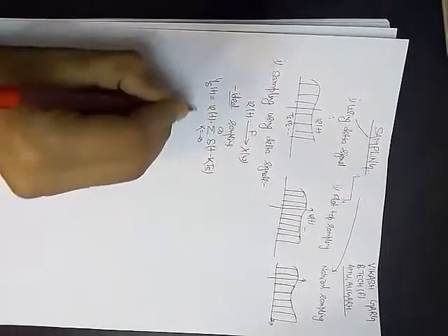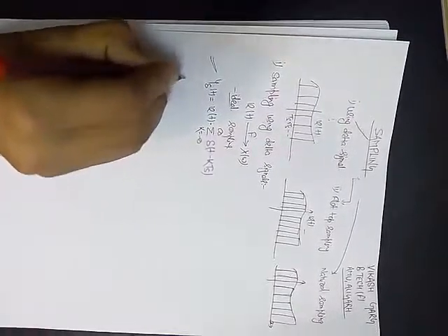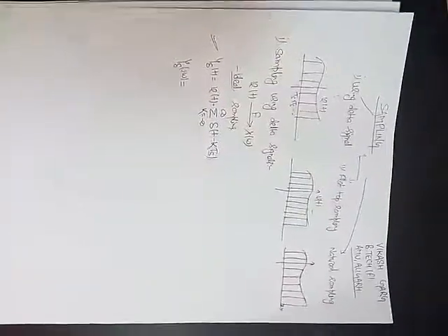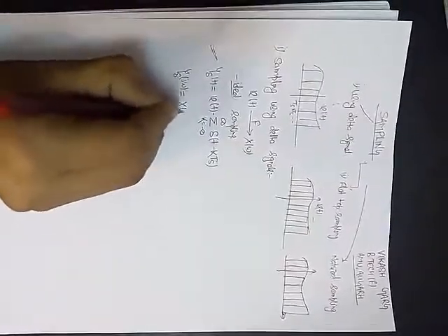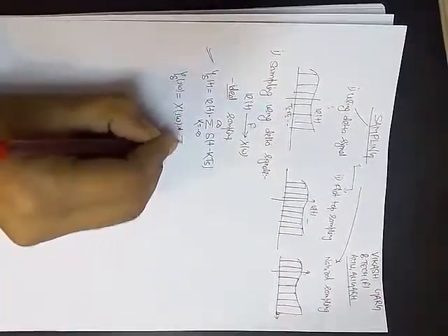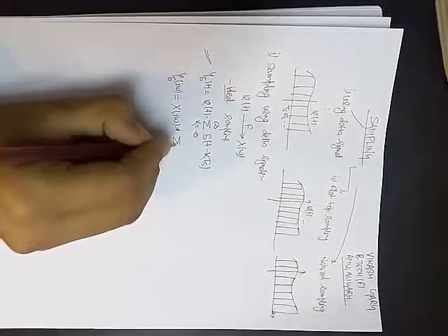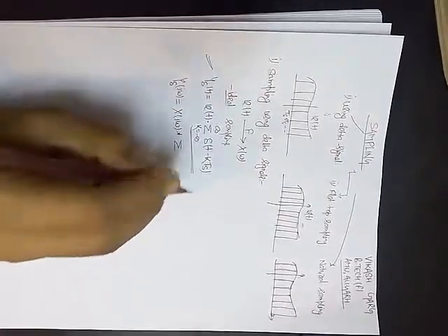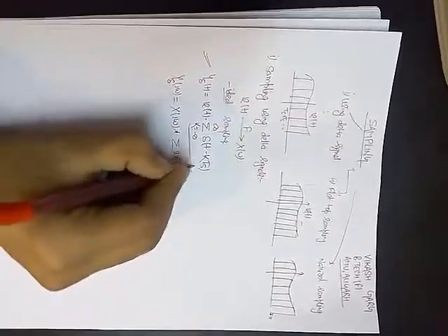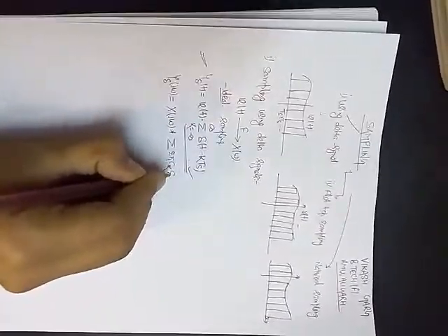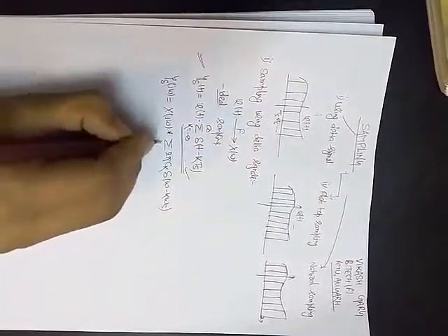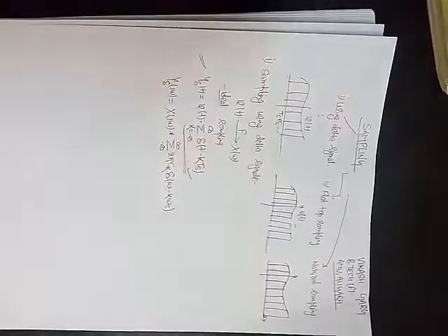If we look at this in the frequency domain, Y_δ(jω) is equal to X(jω) convolved with the summation, which in the frequency domain becomes 2π c_k times the series of delta functions δ(ω − kωs), from minus infinity to infinity.